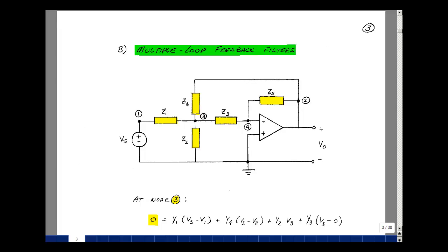We're going to do that with a step-down transformer, which uses 2 coils. If we have a coil in our circuit, we can magnetically couple to that transformer, which has a frequency of a multiple of 60 hertz, and that'll show up in our output, and that would have a horrible sound. So we're going to try to avoid using inductors if at all possible in audio circuits.